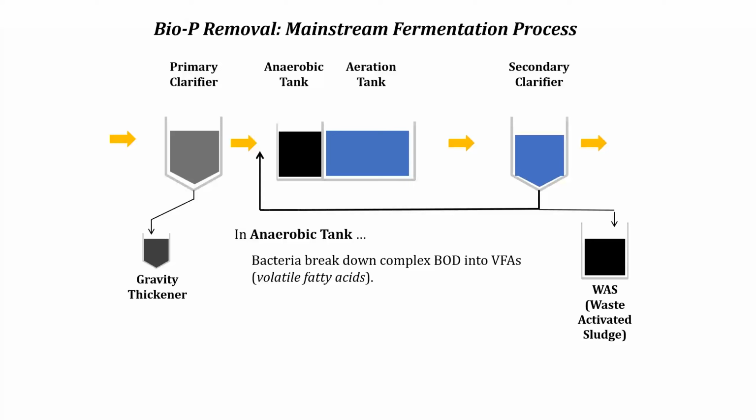For nitrogen, it's 5 to 1. So if you've got 20 parts of nitrate you're trying to remove, there's about 100 parts of BOD. In my hypothetical here, I added 75 for phosphorus. That's a lot of BOD that's getting removed before we even get to the aeration tank. So often that is the limiting component. And so we've got to look for ways to boost that BOD.